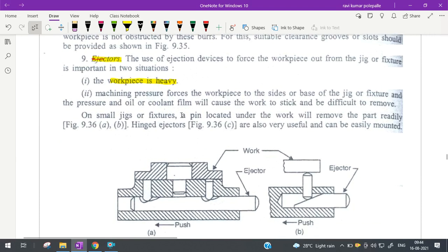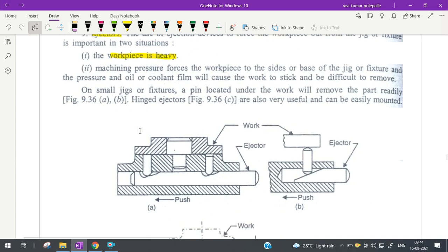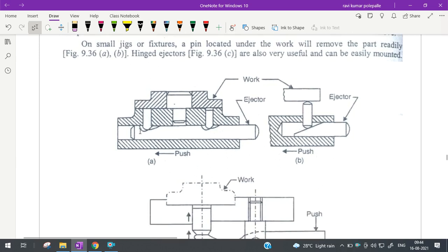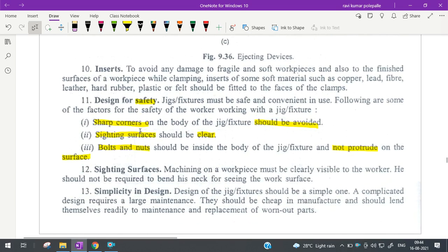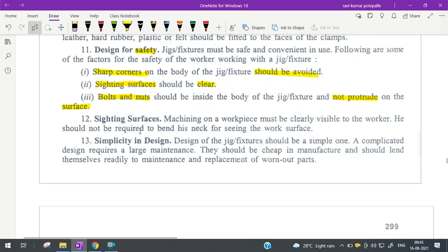So next we shall talk about the drill jigs. Here we have to talk about the difficulties in the drilling operation. When thrust force is applied, one should understand that the two component forces in drilling are the thrust force applied along the axis of the drill and another force, which is torque.